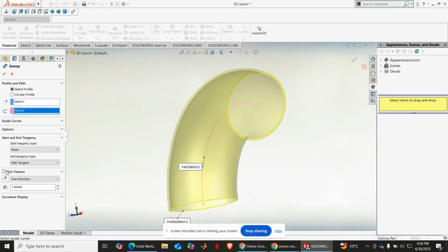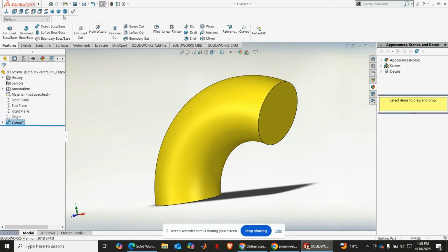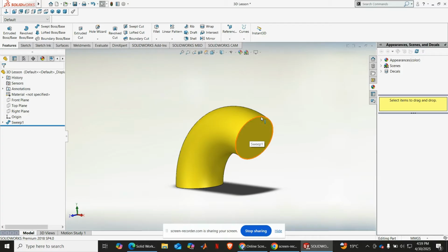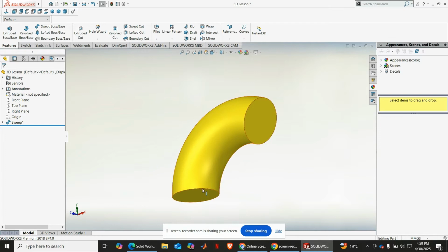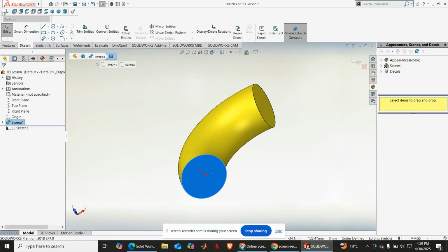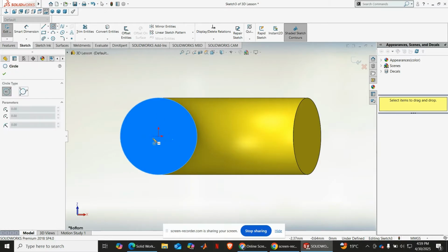Lakini, let's say you want to create, so check. So let's say you have swept bows feature like this, and you want to create a hole here that is not similar diameter as this. So let's say we create a smaller hole here, right? So what we can do is we can go back to this face, right, and say sketch, okay, and then we can sketch here. Let's say normal to. We can sketch here our profile of a small hole that we want to extrude the cut.